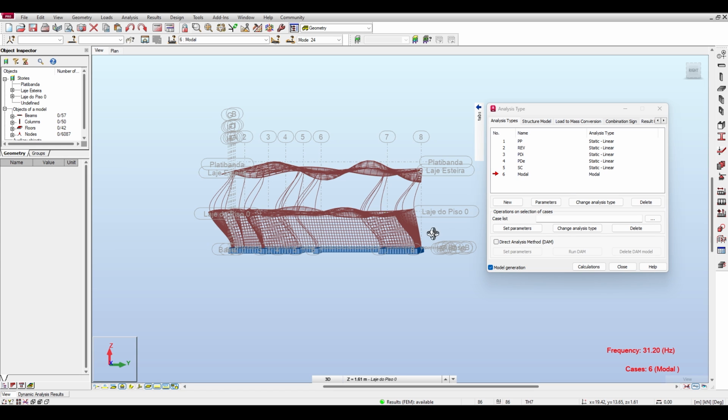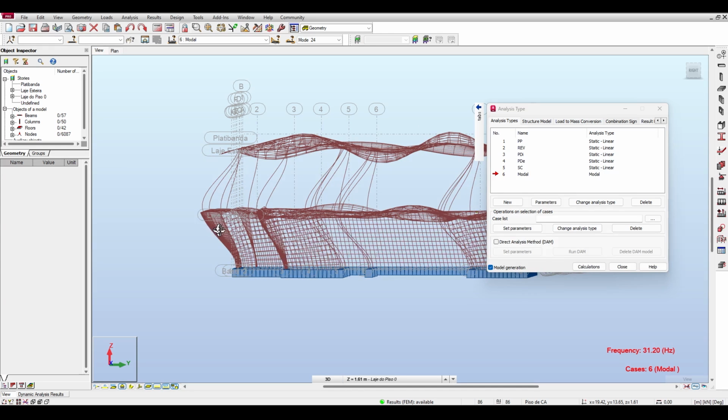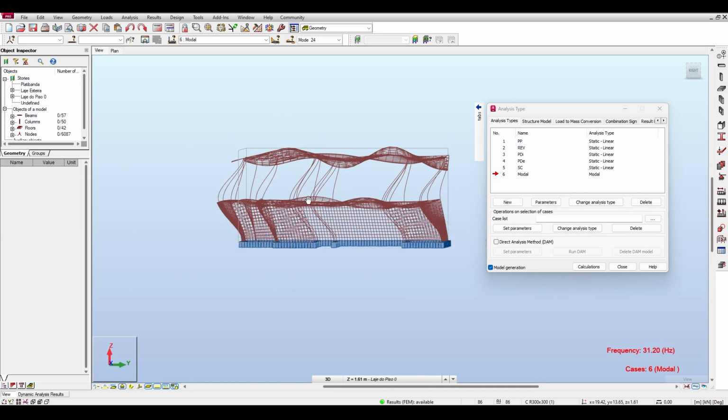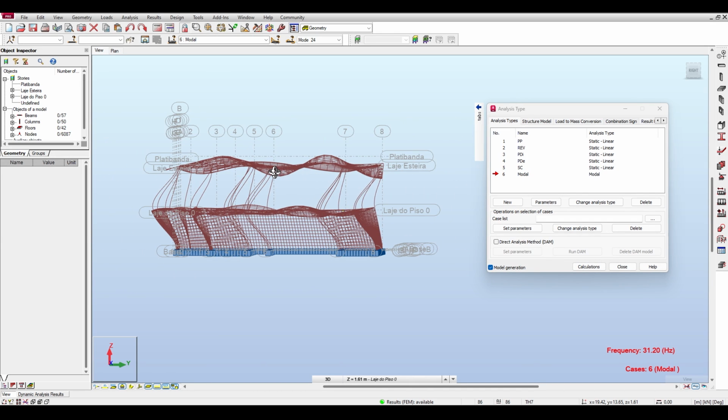You can see the walls are moving, but in reality, this wall is retained by soil, and this wall may be retained by soil. So I think even the model analysis here might not truly reflect the structure in the field, because the retaining walls underground might not be prone to vibrating because they are held in place by the ground itself.